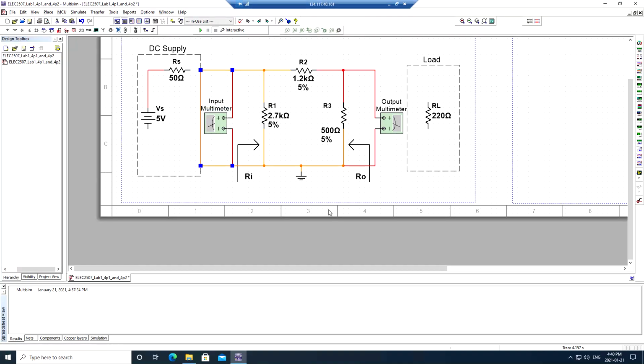All right. Now that our input terminals are shorted, we can go ahead and run this simulation once more. Now we can open our output terminal. Our output terminal is now measuring our output resistance, because our input terminal is shorted. So I can see that I have a certain value here for my output resistance. This should correspond to something that you calculated in the pre-lab.